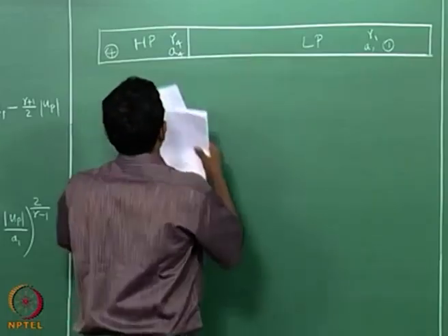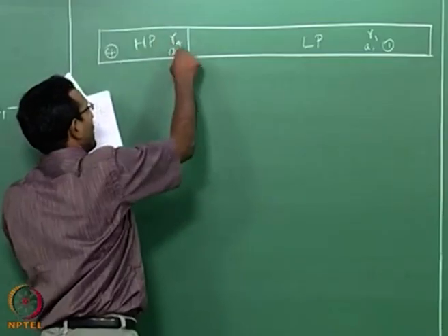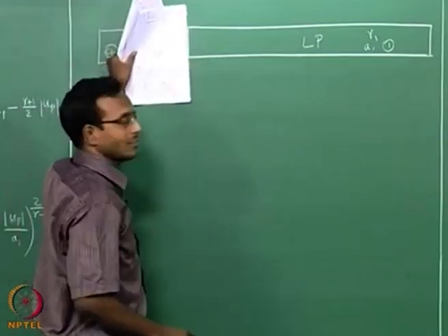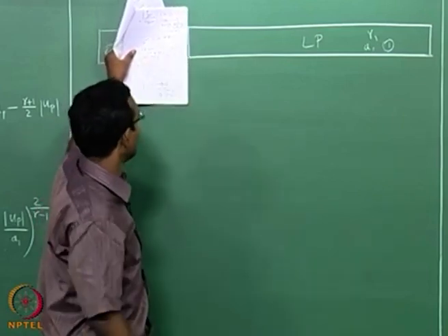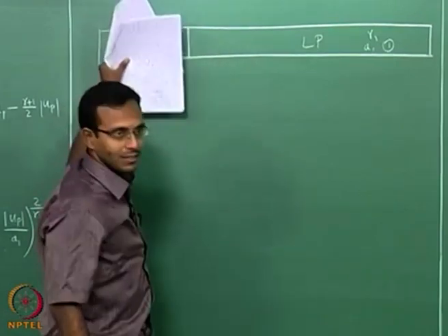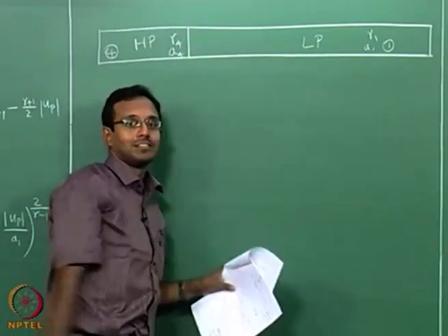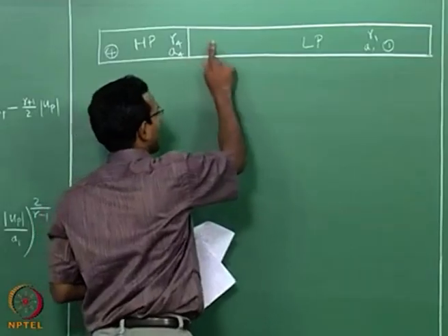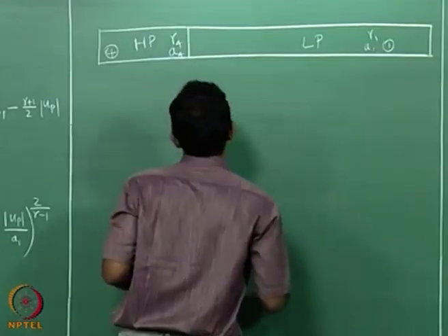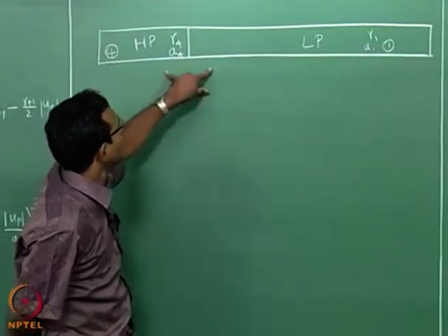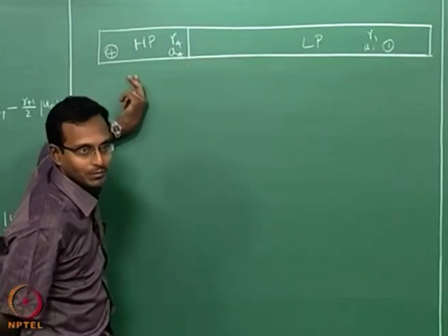Now I will look at it the other way. In here there is a huge high pressure gas sitting here, and suddenly it is going to be pushing at t equal to 0 onwards. Okay? If it is pushing against this low pressure gas, then I am going to have the other problem of a piston traveling against the flow, and thus going to develop a shock, and the flow is going to go behind it this way. Okay? So overall what is going to happen in here? I am going to have a shock traveling this way and a set of expansion waves traveling this way.